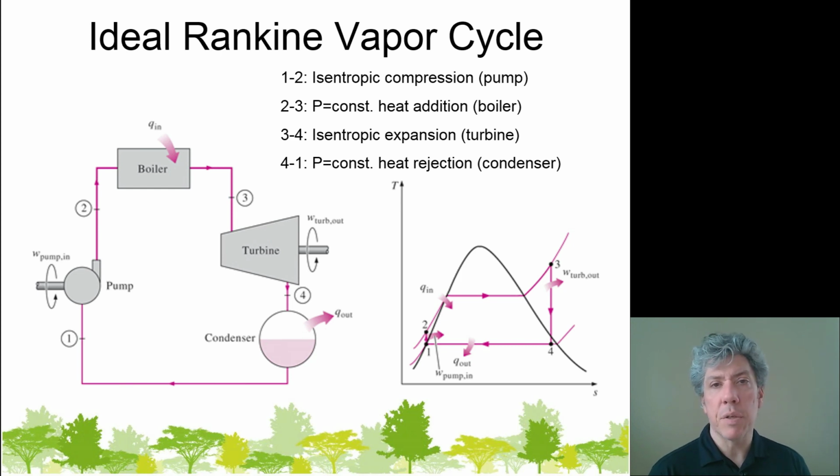And that's pretty easy to accomplish. That constant temperature process is easy to accomplish because the pressure in the condenser is constant, and so the temperature would be constant since there's a vapor-liquid mixture there. And of course, it's pretty easy to make sure that the only thing that comes out of the condenser is saturated liquid. You just need a steam trap, and those are commonly available items.